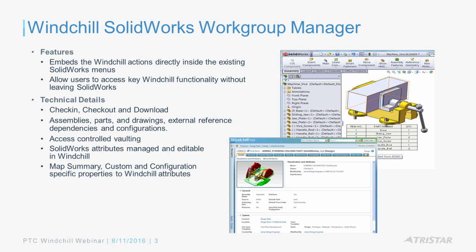They're always being added. The other nice thing that Windchill can manage is some of the attributes coming from the SolidWorks parts. So things like materials, descriptions, project numbers, finish types on the parts, weights, all of those can be mapped when you're uploading this into the Windchill system. So then in the Windchill table, you can do searches, or you can actually see those attributes from those parts. You can also edit those in Windchill.